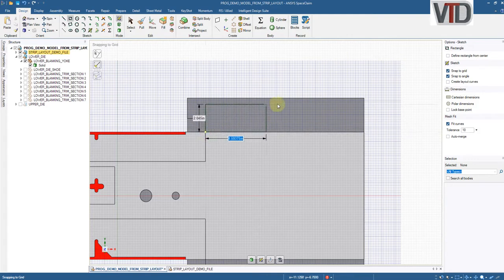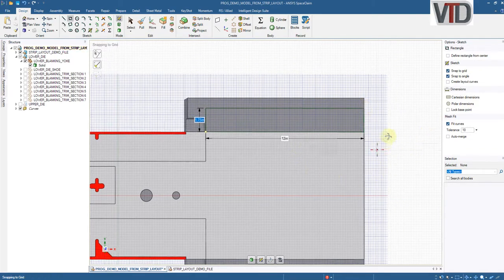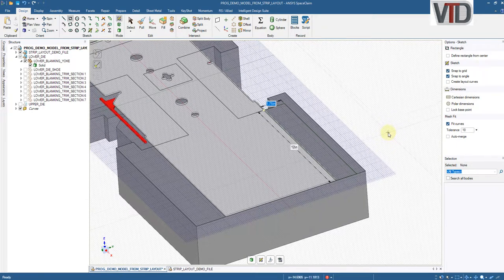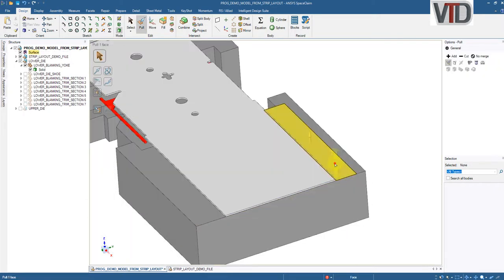and I'm going to just make a rectangle here, and we want it to be 12 inches. If I tab, I can tab between the two dimensions. I'm going to make this 1.75, and that's going to be 12. So this is the stock guide minus the lip at the top of it.